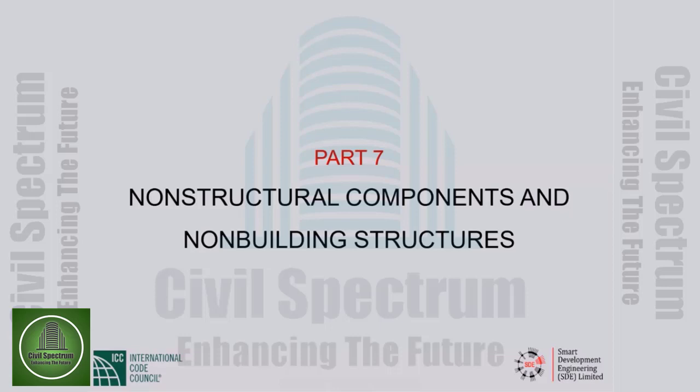In a different period range, the spectral pseudo velocity is about constant, and in a third period range, the spectral displacement tends to be constant. I know that is not a satisfactory answer, but that's the best I can do.